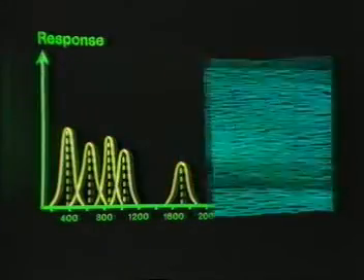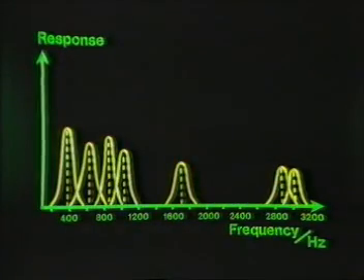In fact, there's a whole series of natural modes of vibration for the board, each with its own characteristic natural frequency. And when the board is forced to vibrate, its response curve is the combination of a whole series of resonance curves centered on the natural frequencies. But there are still gaps, frequencies at which the board doesn't amplify. So a simple rectangular plate wouldn't be ideal for a violin.